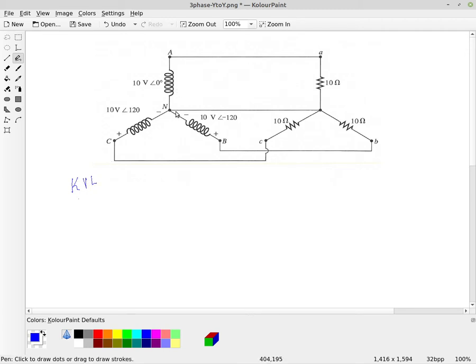And so if we started here at neutral and went up through the first coil to point A, and we go down through the resistance here, and then down through this resistance to point lowercase b back to this point, right? And so that would be a complete loop. And so we could write the voltage, and the question then becomes, what is the voltage VAB?